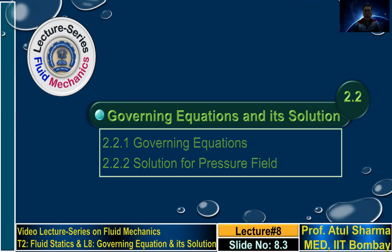In fluid dynamics, we'll apply both mass and momentum conservation, but here in fluid statics, we'll apply only the momentum conservation. And using the law, finally, we apply the limit delta x, delta y tending to 0 and obtain a differential equation whose solution is a functional relationship. So here in this case, for fluid statics, we will derive a first order ordinary differential equation, and the solution will correspond to pressure as a function of y, which corresponds to the height of the fluid.